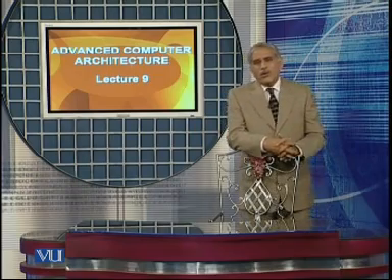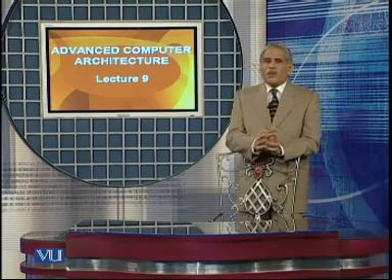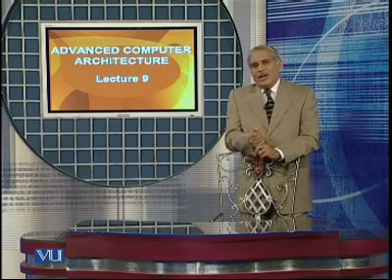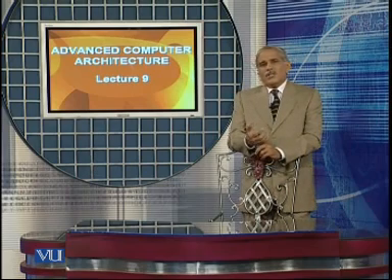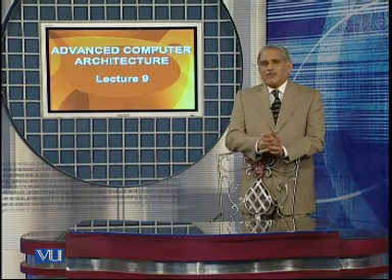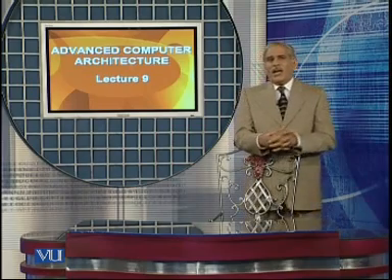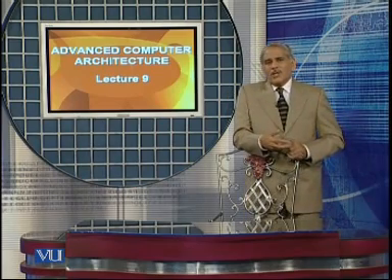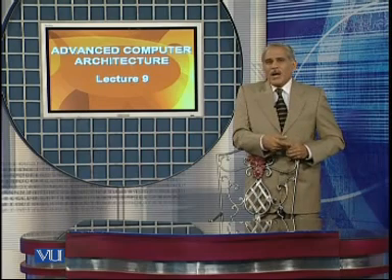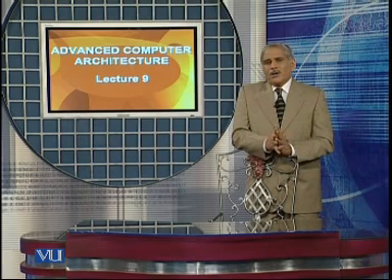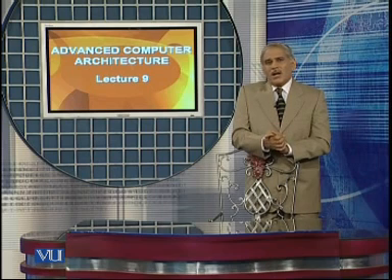When instruction decode and register read operation is performed, the instruction fetch circuit, execute circuit, and the memory reference circuits or the write back circuit are not doing anything. Similarly, during the execution phase, the instruction fetch is sitting idle. The instruction decode is sitting idle. Write back is idle. So this shows that only one part of the whole system is in use, and most of the parts are sitting idle.